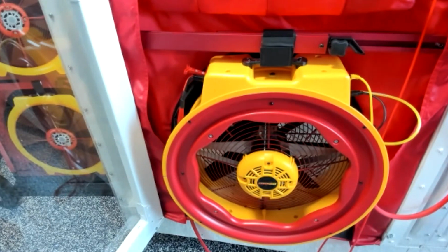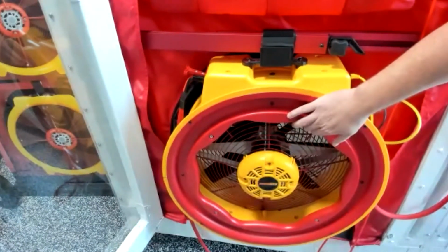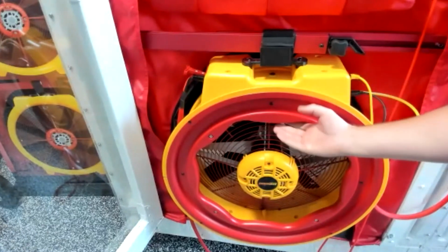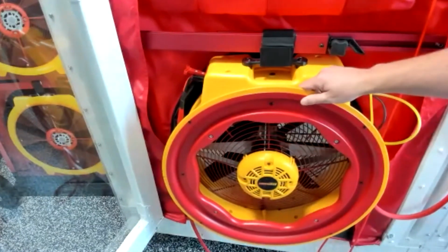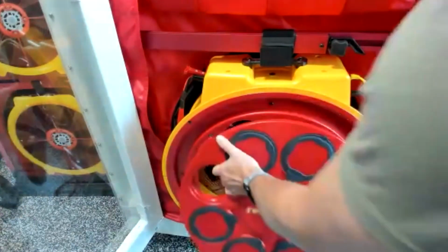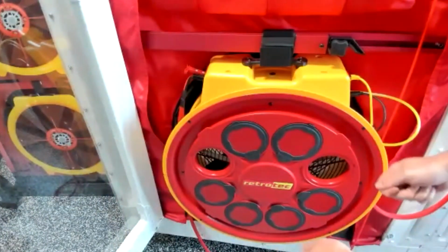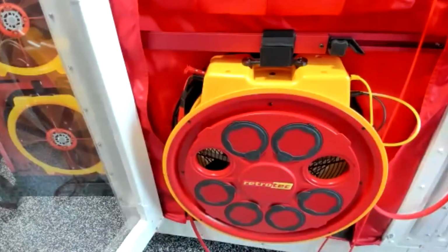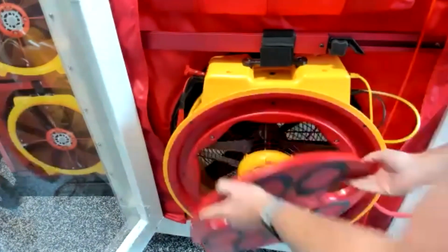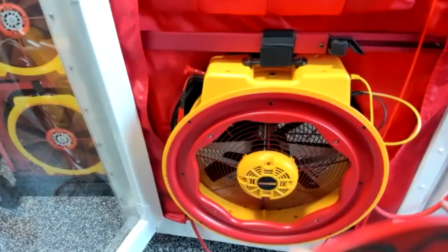If I'm testing an existing home I've never been to before, I usually start at ring A right here, and then the manometer will tell me if I need to go up. I can open this all the way up by taking this off, or I can go down by putting the B8 plate on and then opening all the holes up to the B8 setting, or shrinking it down some more. So the gauge can tell me which direction I need to go if I'm not getting the reading that I need for reading A. I'll show you an example here in just a second.